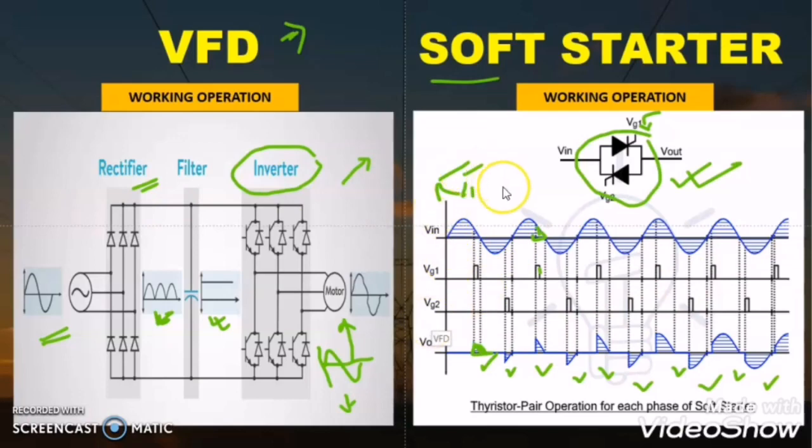So the voltage is gradually increasing, so the motor also starts gradually, and this is called soft starting in electrical terms. The motor does not start in a moment, because if the motor started from rest to its rated speed in a very short time, might be 2 or 3 seconds, then there would be two issues. One is the electrical issue and the second is the mechanical issue.